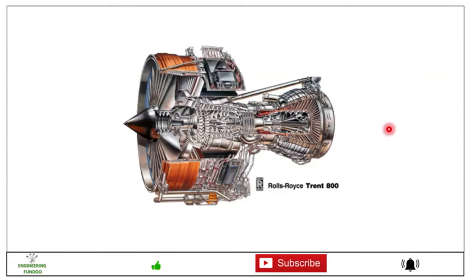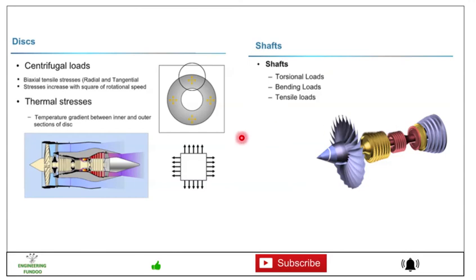Friends, this is the general image of the Rolls-Royce Trent 800 engine. Now let's go to the different parts. Then we have the disc, and this disc is subject to centrifugal loads and biaxial tensile stresses, radial and tangential, and stresses increase with the square of rotational speed.